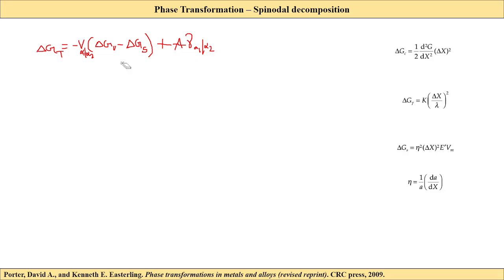So that's why you are standing at equilibrium. Now when delta G is negative, that means whatever volumetric free energy has been obtained by transformation will be more than sufficient to accommodate our strain and surface energy. So those reactions are favorable reactions, because they will transform spontaneously without needing any external help, right? Because the system has its own energy, so it can transform. These are the three cases.